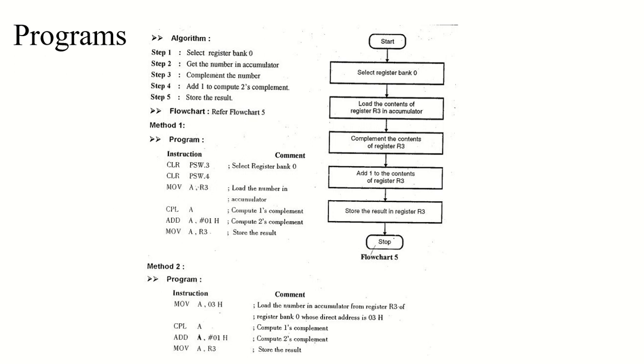If you are thinking about a special program or a special instruction to find the two's complement, there is no special instruction to find the two's complement in the 8051 microcontroller. But remember, I told you how we find two's complement. You first find one's complement and then add 1 to it.